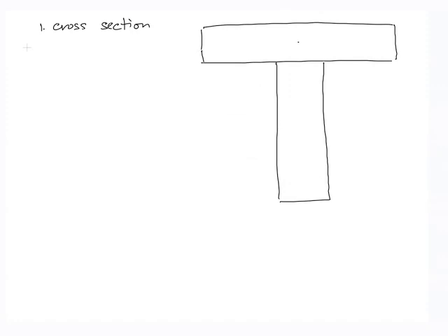In red, I'm going to label parts 1 and 2 of the cross-section, and I'm going to label the centroid locations of those respective pieces of the cross-section. So this dimension right here, that's 1 inch. This dimension right there is 4 inches, and of course they are oriented on this center line right here, just like that. Okay, so our first goal is to find the location of the centroid of the composite section, and that's going to be a function of the area and the centroid location of each section.